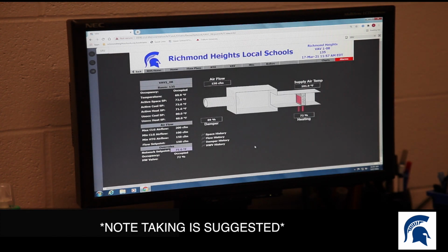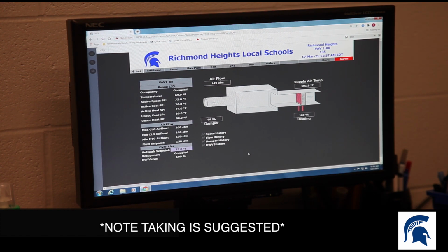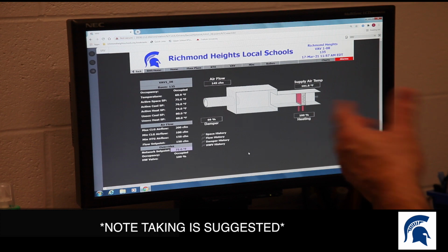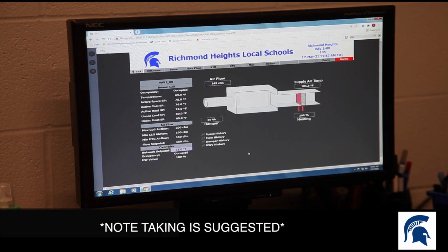And now it'll go back to 75, and this valve should open up all the way. Yep, it should whack back open 100%. Once it goes back to that, you should be able to release that override, and it'll stay at 75. So we could adjust every thermostat in the building, or just the ones in that section? You have to do each one individually for every rooftop unit. So how many were in this unit? I think there's 80-some VAVs total, somewhere around there. Right, so everything went back to 100%.